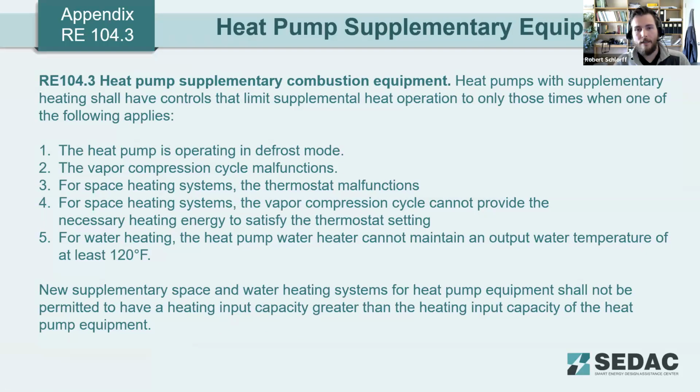And then we have one last slide here that covers a little bit more about supplementary heating. The stretch code contains some requirements to control that supplementary heating and to make sure it doesn't run away from us, or that it is only on when it absolutely needs to be on, because supplementary heating is oftentimes electric resistance heating, and that can add up if it's running for a consistent amount of time. So the stretch code does have specific requirements about heat pump supplementary heating. Since we're right on time here, I think I'm going to leave it there and we can see if we can answer some of these last questions.